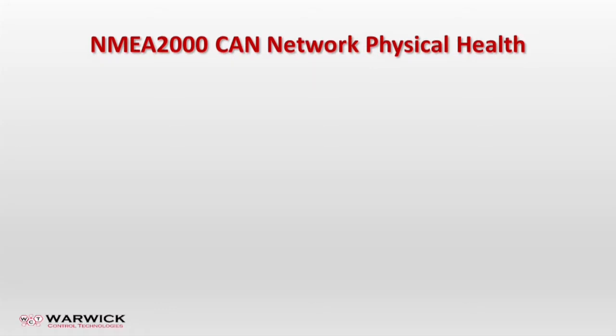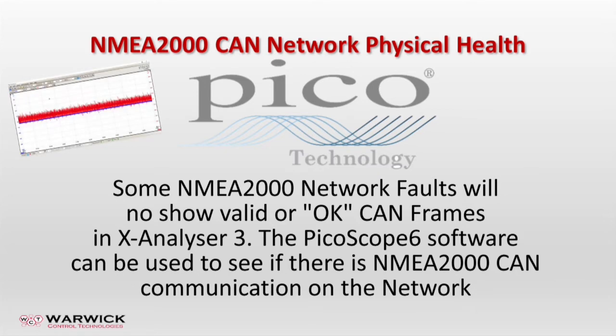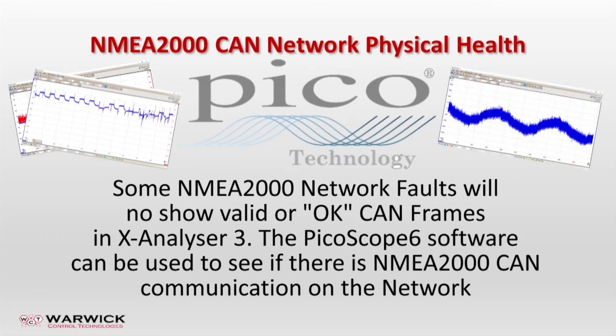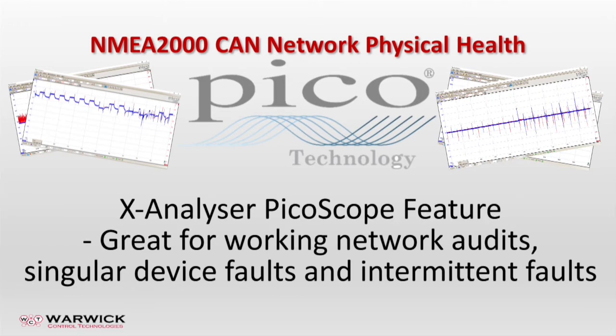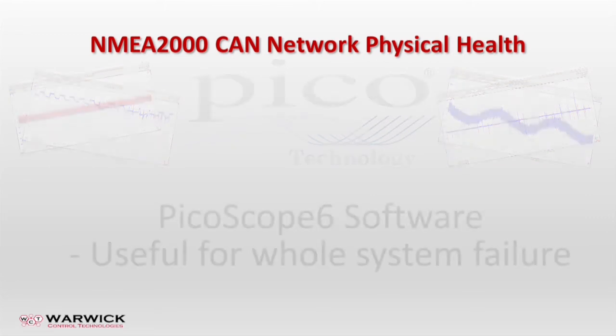Some NMEA2000 network faults will not be decoded by the X-Analyzer's Picoscope feature. However, if no valid or OK CAN frames show, you can then use the Picoscope 6 software to see if there's any electrical signals being produced on the NMEA2000 network. So X-Analyzer scans the network and grabs one example of each CAN ID waveform on that network, useful for whole system audits, whereas the Picoscope 6 software is useful for entire system failure. The X-Analyzer will not decode.